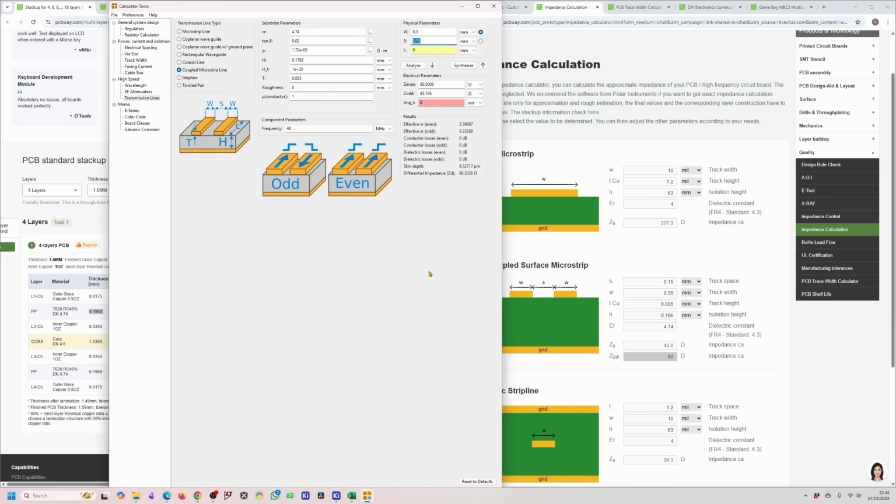So that's something that you basically need to communicate with your PCB supplier to make sure that you're getting that right. So if you want something specific, impedance controlled, you need to speak with your PCB supplier and let them know that, for example, let's say in this case it's 0.3 tracks. Then let them know that 0.3 tracks need to be impedance controlled to a differential impedance of 90 ohms. And they will basically advise you on how to do that. And they will tune their processes and materials for you to be able to meet that, if possible, obviously. Now, USB 2.0 is not that sensitive anyway, so you can basically ignore it.